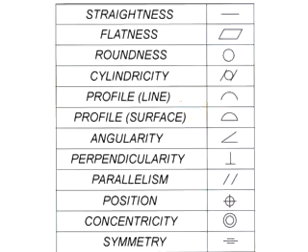The next three are what's called related geometric tolerances, and that's because they have to relate to another surface to be able to exist, and that's angularity, perpendicularity, and parallelism. Now, something that is angular has to be angular in relation to something else. The same goes with perpendicularity and parallelism. A thing or surface cannot be parallel to nothing.